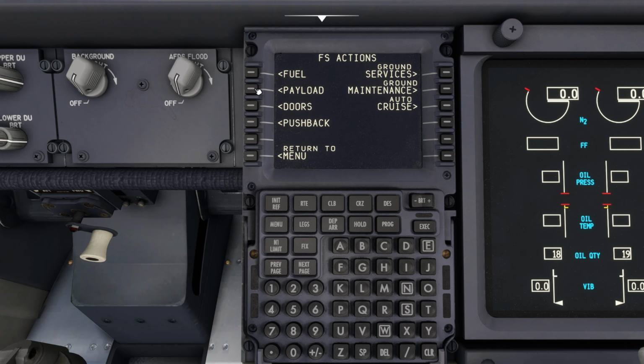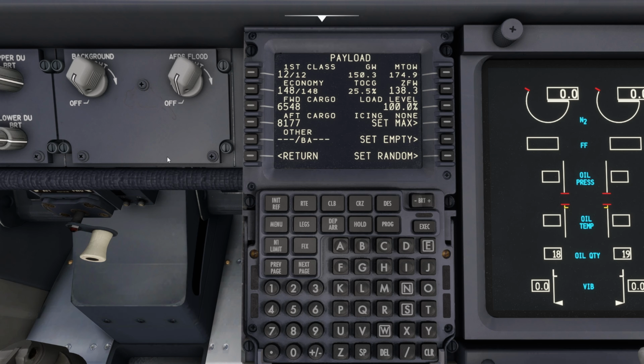And we're going to go ahead and click on payload. So how do we get our payload? Same thing. We head on over to SimBrief and we are going to take a look at the estimated zero fuel weight, right? So you're going to have to have your SimBrief flight plan open so you can follow along. Look for the title in the load sheet section that says estimated zero fuel weight, ZFW. That'll be your figure, right? So for us, it's 118,855 pounds.